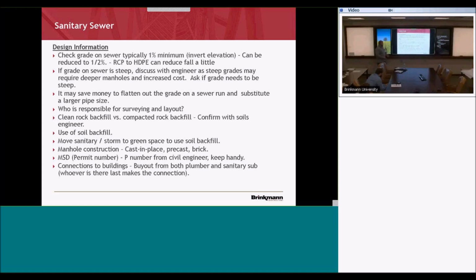You can't always do it. A lot of times, once you get underneath your building pad or parking or underneath the drive lanes, you can use clean aggregate. So it's just a thing where you've got to look at each plan, each spec, and see what it allows you to do, and go from there. The clean aggregate's nice when you can use it because it's fast. It goes in quick, and they can get a lot done, and then you're closer to home with that.